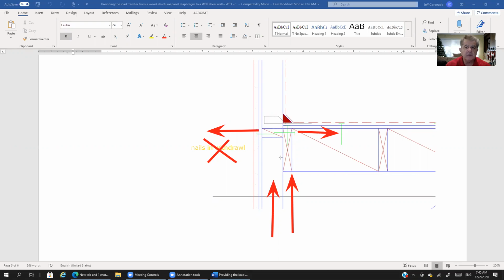Plus, there's a certain bias towards a nail in withdrawal, and that is that ultimately, as you activate the nail in withdrawal and go through cycles of it being loaded, unloaded, loaded, unloaded, eventually it starts to wedge out, which causes tearing in the roofing, depending on what other assemblies are going on around it.